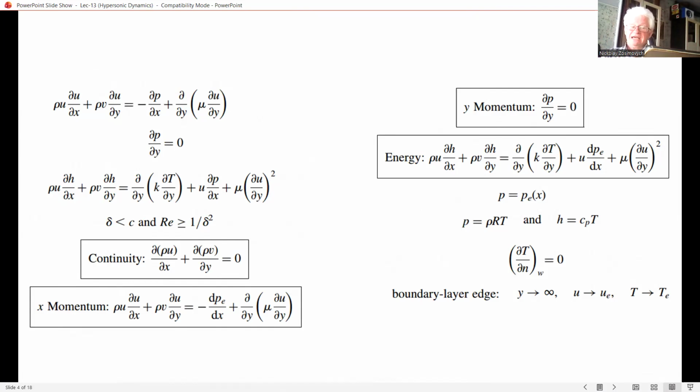That is, the exact boundary layer equations are used, but errors are introduced via the numerical solution in the form of truncation and round-off error. And hence, we can readily state that the numerical solution of arbitrary non-similar boundary layer is fairly common practice in hypersonic aerodynamics today.